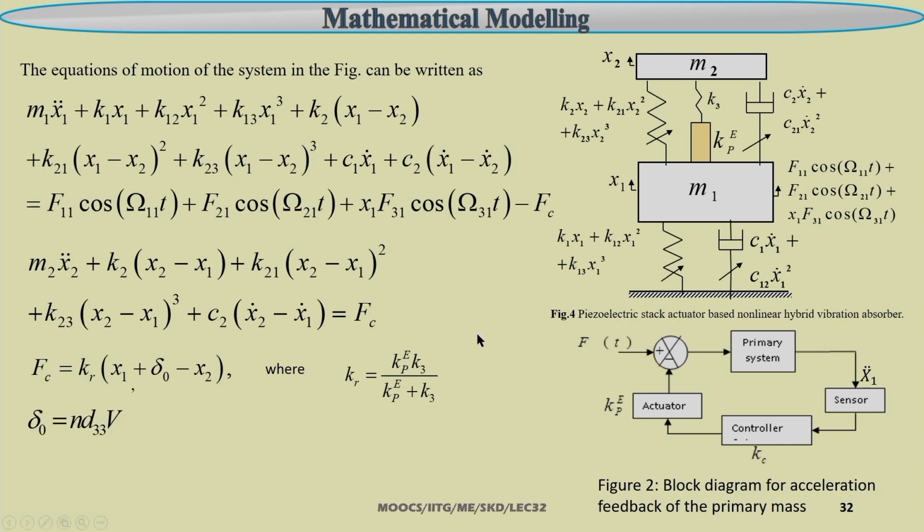Here delta 0, that is the displacement of the piezoelectric stack actuator, equals N d33 V. Like the previous case, here also we have taken the same way, but this control force is written equal to K R into x1 plus delta 0 minus x2.